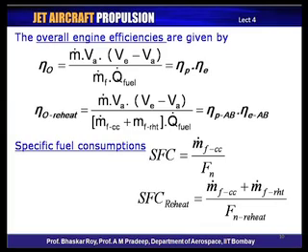If you have a lower efficiency of either energy efficiency or propulsive efficiency, your SFC is going to go up. Hence, you would be constrained to create thrust at the expense of more fuel burnt, or your thrust production is going to go down. These are the various pushes and pulls of the operation of a typical jet engine, and this is what an engine creator would have to look into right in the beginning.